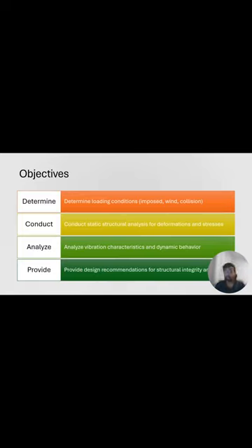The objectives of this project were to determine the loading conditions: imposed load, wind load, collision load, self load, dead load, conduct a static structural analysis for deformation and stresses, analyze the vibration characteristic and dynamic behavior, and provide design recommendations for structural integrity.